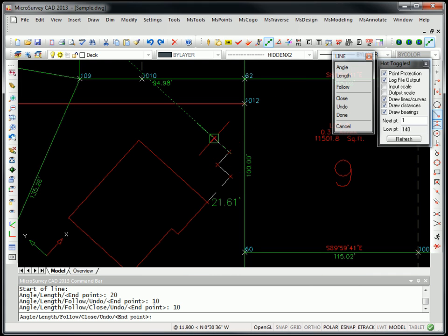And one of the features I want to show you here is you should see there's little red X's that are appearing in the drawing, and those are called temporary markers. And from those markers, what they do is it'll project those green lines from them, and those help you draft lines that are exactly the same as using the ortho mode with your F8 key.